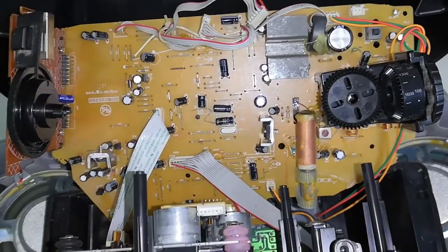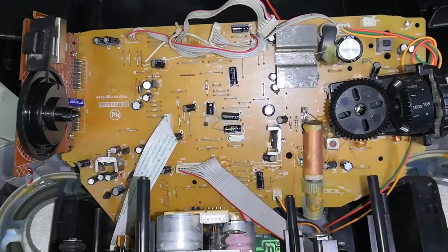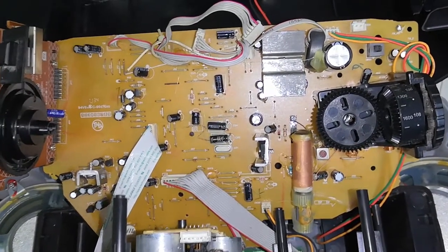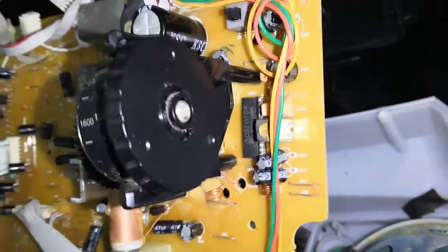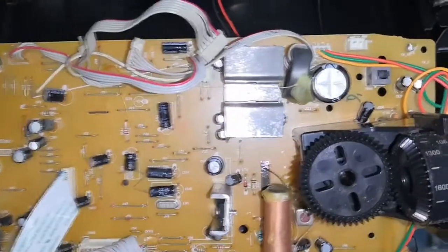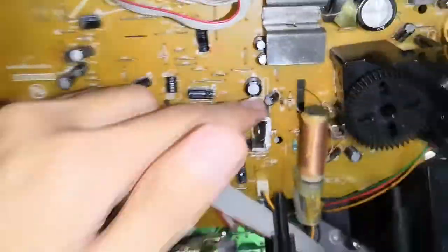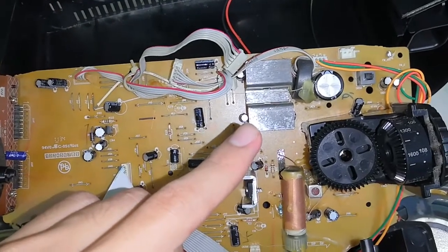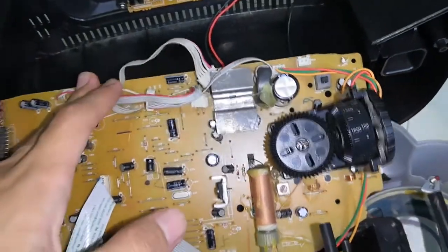And as I said just now, it is not a new technology, so it does not use a lot of IC. We can still see a lot of capacitors down here and also resistors, but it actually has two ICs. The first one is down here. It is an IC601, which is a power distributor IC, and also right below the large heat sink here, we have another IC, but I'm not sure you can see or not. It is a thermal electronic IC. That's why it is under the large heat sink.